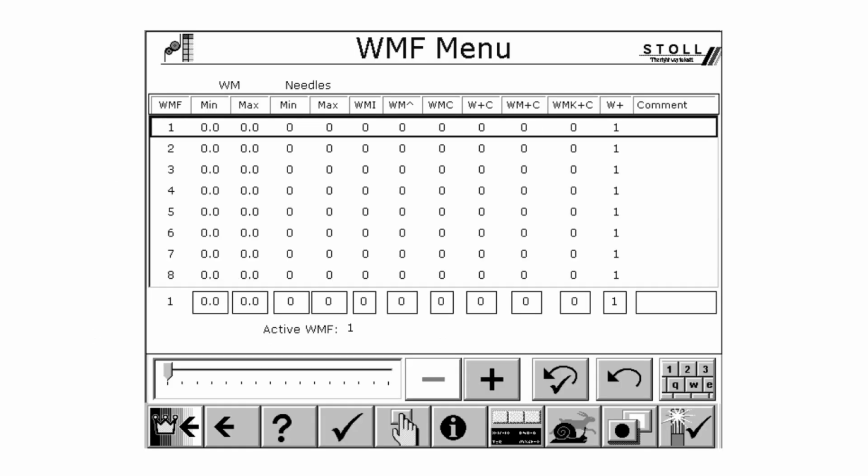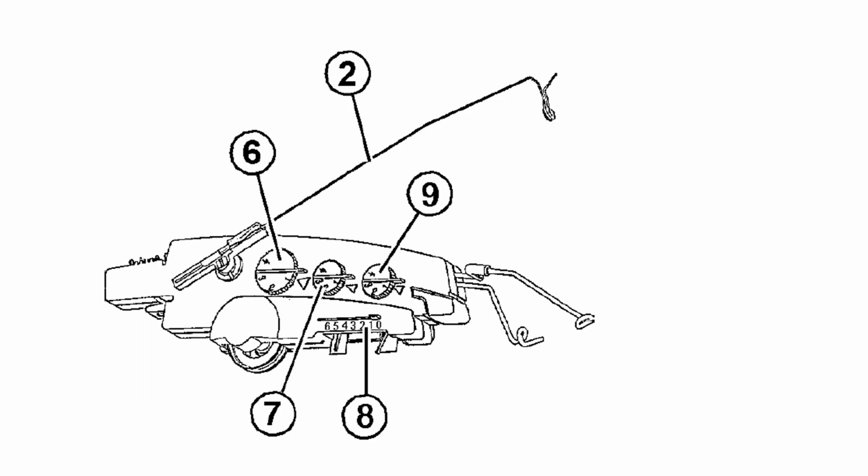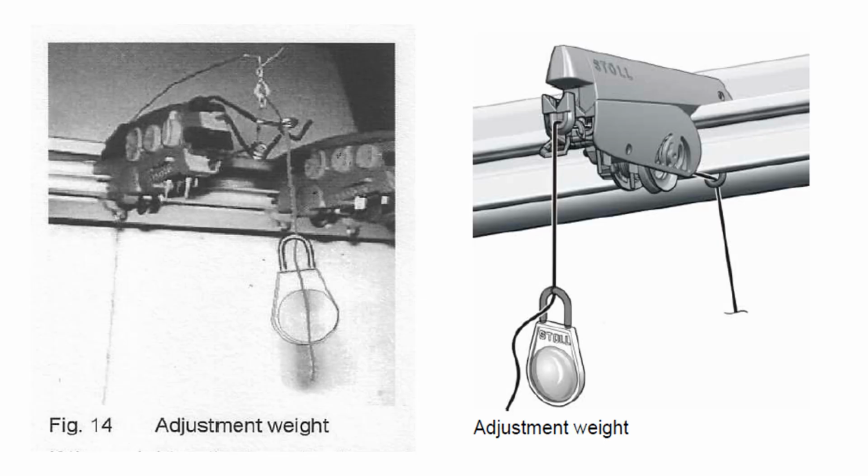The factor that affects the most is the yarn tension, controlled by the spring brake on the yarn guide. Though the dial for this brake is marked, there is no way that these marks tell the operator how much the value of the brake is at any given time. The only way to ascertain this is by using a small standard weight to check the brake value, as shown in the picture. But how many operators are aware of this? And how many use this? Close to zero.